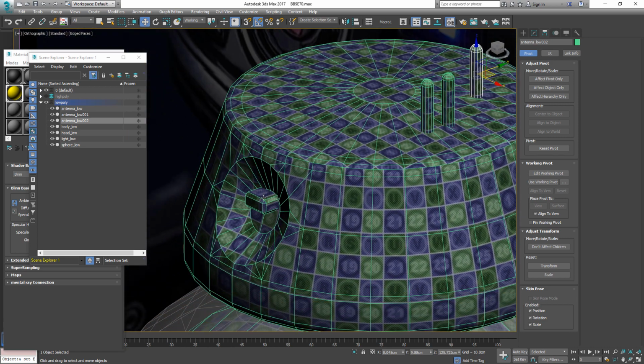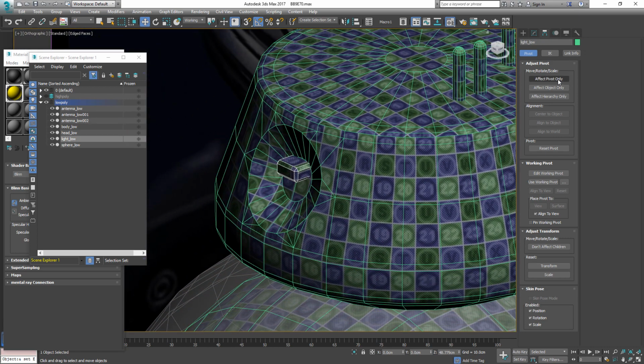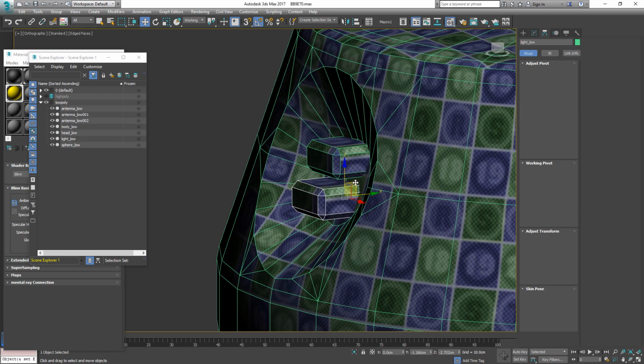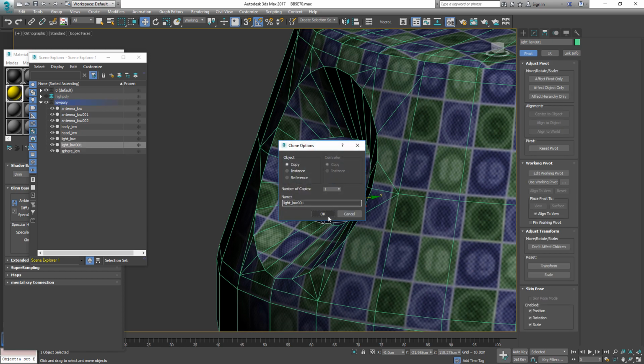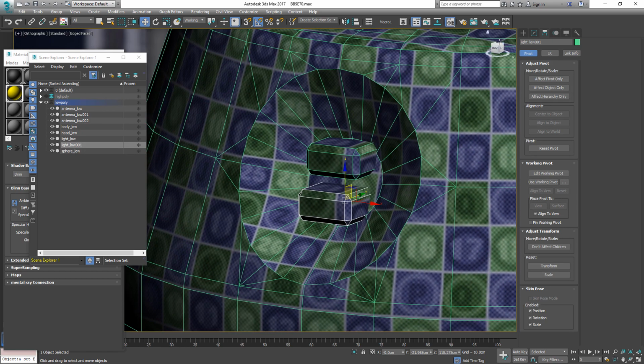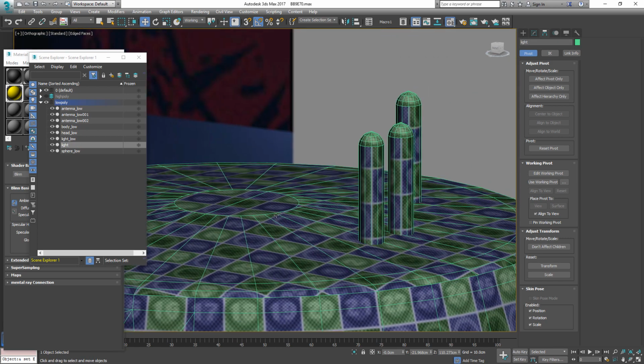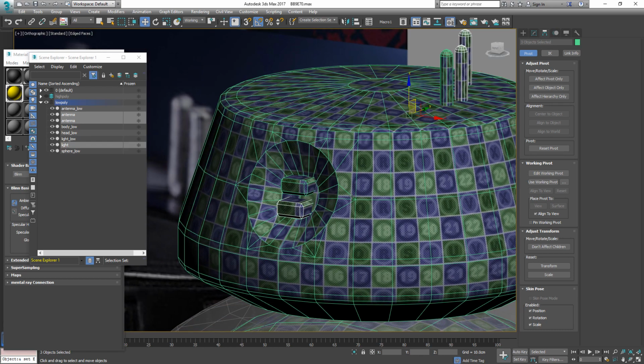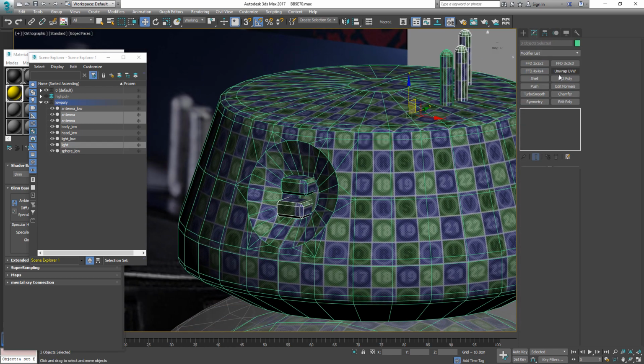And we have to do the same thing here for our light. I'm gonna also center the pivot to object here, so that it's easier then with shift to make a copy of it. Copy that. And now let's make sure we just call that light. And that piece here just antenna, so that it doesn't get confused with our naming convention, because we only want to bake the ones where we actually have a high poly piece for.